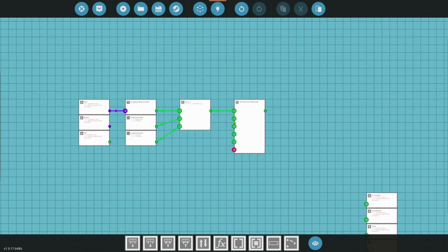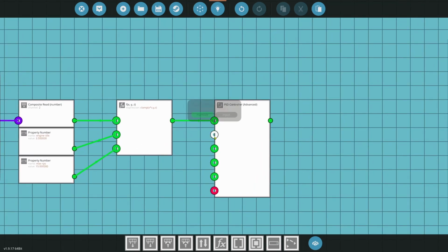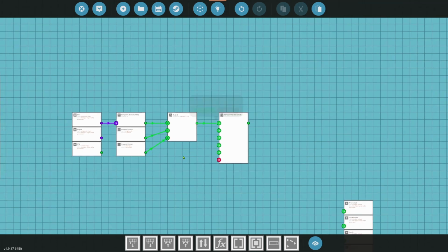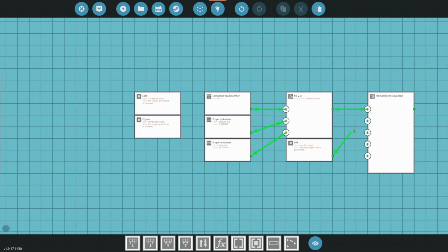What our set point is doing is setting the value that we want. It's saying, hey man, I want you to go 3.5 RPS. The PID then says, okay, where am I currently at? That's your process variable. Your process variable is where the engine is at. So we're going to use the RPS here. We'll go over here to RPS, and we'll plug the RPS into